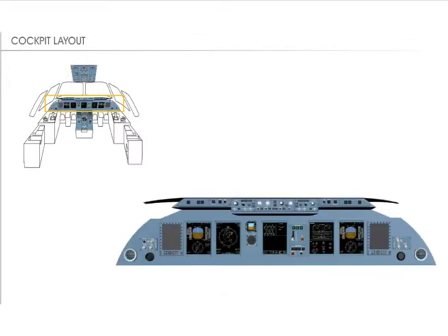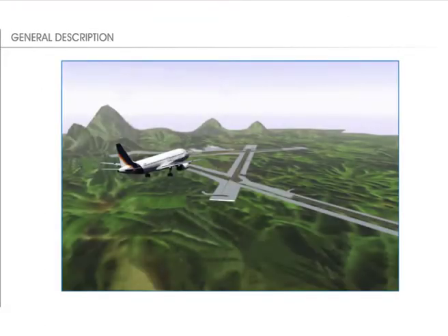The flight control unit includes the electronic flight instrument system controls, and is used for control and monitoring of the auto flight system. It is located on the glare shield. The master warning and caution attention getter lights are also located there.